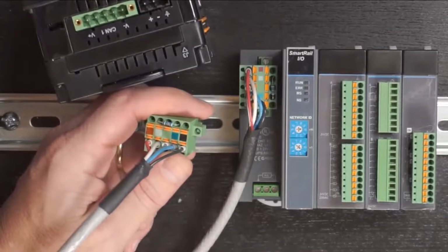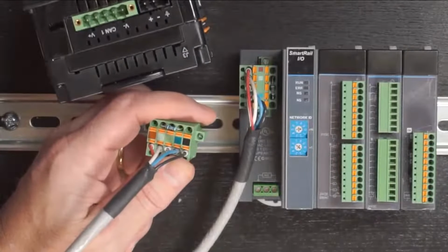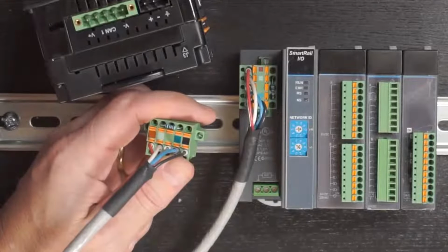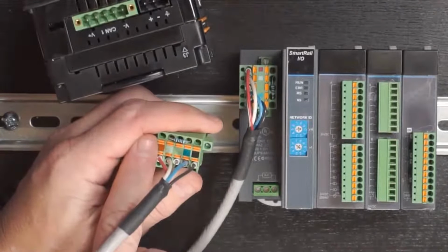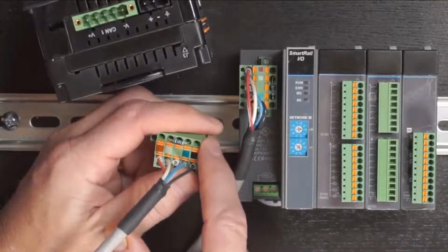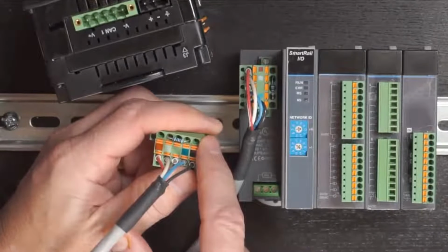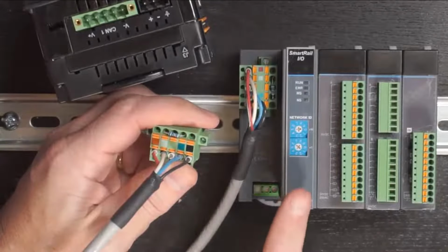Now, one important point here I want to make sure you don't miss. I have yet to add 24 volt DC power to this particular cable. All right, it has not been added yet. So what I'm going to do, if I were permanently installing this, and I will be a little bit later, is I will be adding a discrete conductor here with plus 24 and another discrete conductor here for common. And then that 24 volts will be used to power the SmartRail.